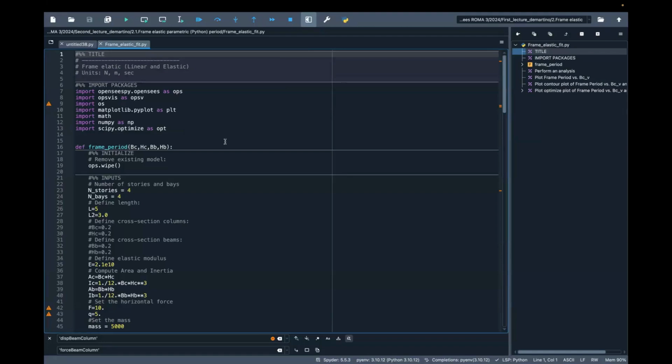And you can see I'm creating a function. Inside Python, to create a function, you need the def, frame period, the input variables represented basically as a list, and then with a certain indentation, you put everything. So once you have a parametric model, you can simply create a function and put everything inside it. That's something I generally do. As you can see in lines 29, 30, 32 and 33, you comment the input variables you are considering, and you transform your structure into a parametric function. At this point, once you have a parametric function, everything is super easy.